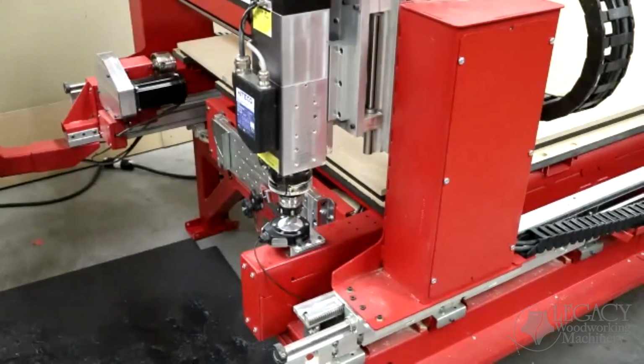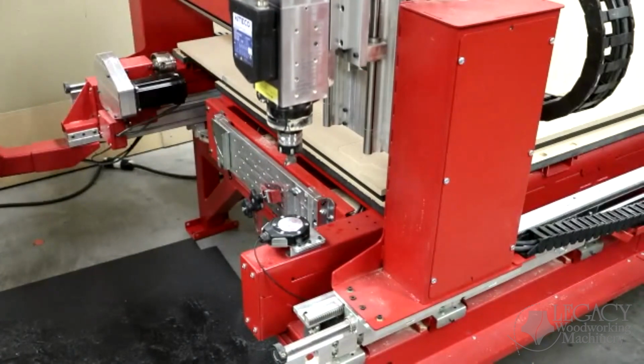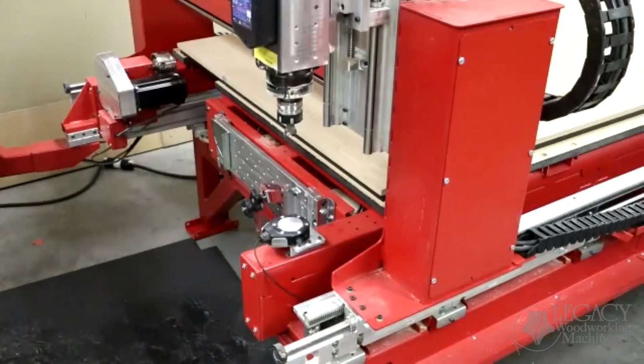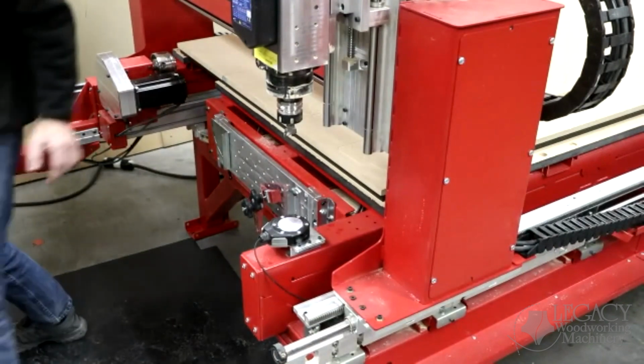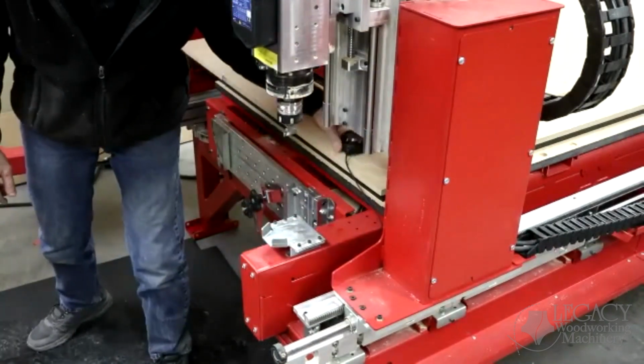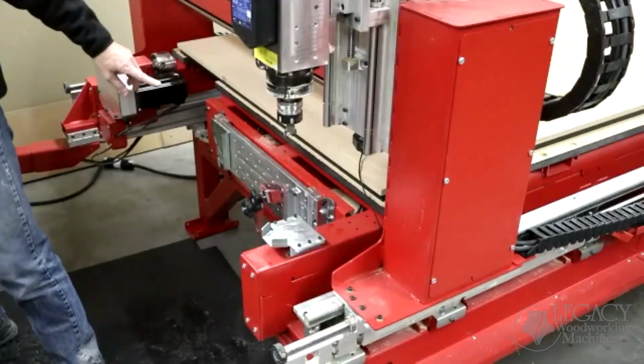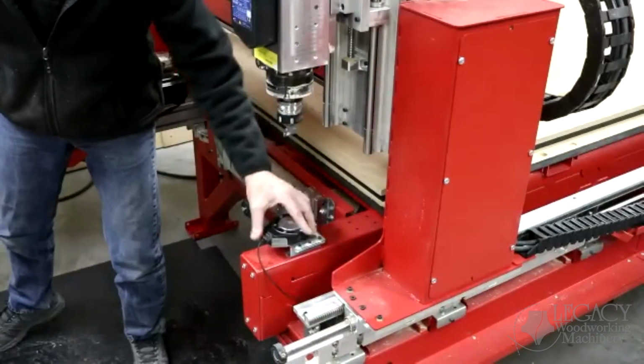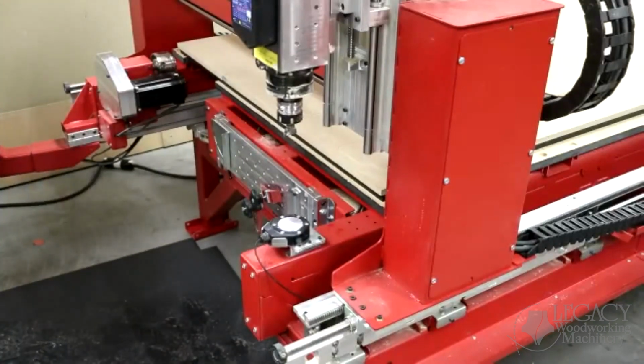So this is how it's working. When it touched off the Smart Tool pad the first time on the table, it recorded a value. So when it touched up here on the top, it recorded the value. Then it came over here and touched off here and measured the difference. Okay. So on this particular setup, my part is higher than the Smart Tool pad by only about 1/8 of an inch. So it would have recorded that number, it memorized that number. It's just making a setting. So it's a 1/8 inch difference.